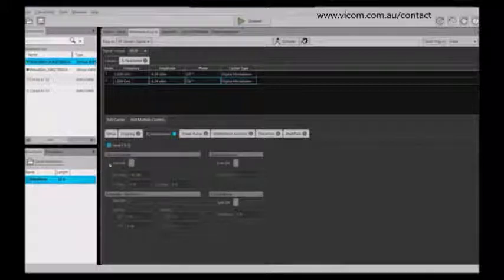You can turn on carrier linkage, so this gives you the flexibility of setting the criteria for that. You can turn on quadrature error, so you can change the phase relationship of your quadratures, your IQ outputs. Nonlinear distortion, IQ imbalance. So this gives you all of the flexibility for these IQ impairments that many customers are using to test their receivers.